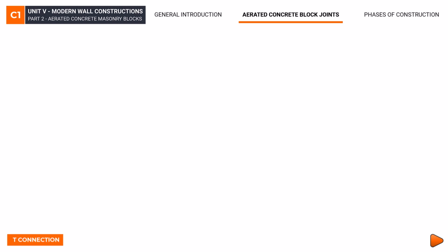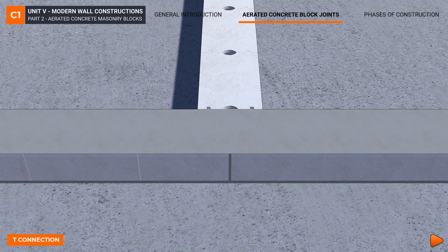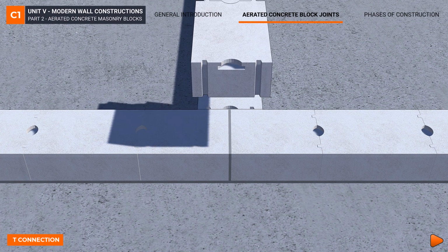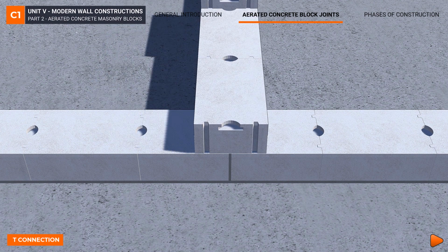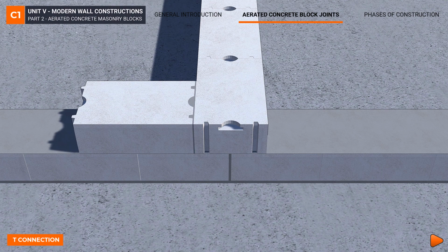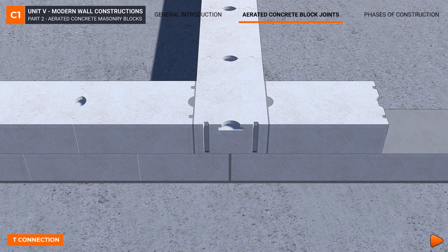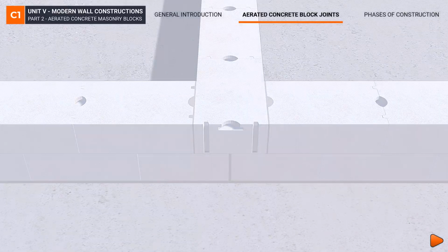2. T connection. In the first course, the connecting wall is already tied to the main wall. We placed a whole element for this. In the next course, an overlap of 22.5 centimeters would reduce the element bond to only 15 centimeters after the connection. Since the wall will be closed by a wall end later, it is better to increase this to 30 centimeters from the connection. To do this, a 44 centimeter cut element is laid down, and from here, the masonry is continued again with a whole block.